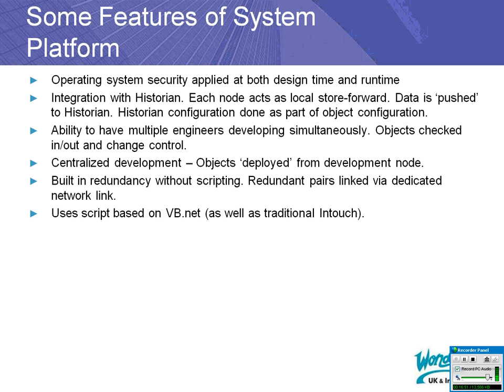It has much more powerful scripting than InTouch. It does use traditional InTouch scripting, but it also uses script based on VB.NET. So you can use a lot of .NET calls within the script, and you can actually mix and match InTouch and .NET scripting as well. It uses InTouch to visualize. The ArchestrA graphics that are created and used are put into InTouch, and anybody who knows InTouch from about version 8 will know that you have an access name called Galaxy built in. This is to link to System Platform.